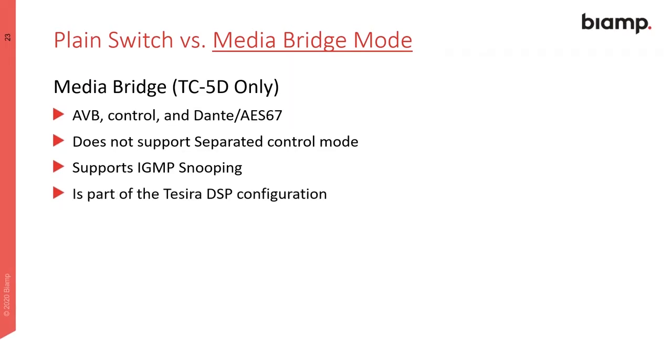Also, it is a part of the Tesira DSP configuration. You will find that the TesiraCONNECT 5D is a part of your device equipment list. You will find it in the equipment list. Why? Because we're going to bridge AVB into Dante in some of the cases.